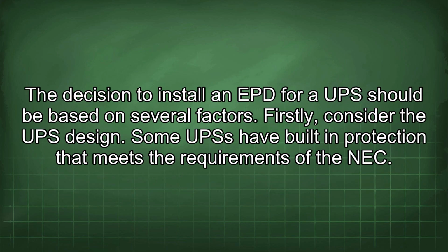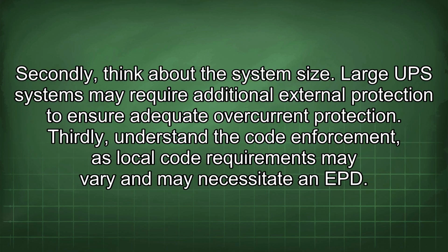The decision to install an EPD for a UPS should be based on several factors. Firstly, consider the UPS design. Some UPS have built-in protection that meets the requirements of the NEC. Secondly, think about the system size. Large UPS systems may require additional external protection to ensure adequate overcurrent protection. Thirdly, understand the code enforcement, as local code requirements may vary and may necessitate an EPD.